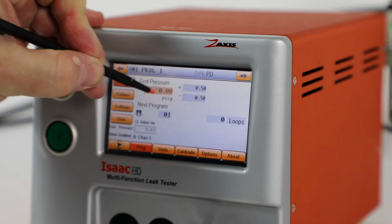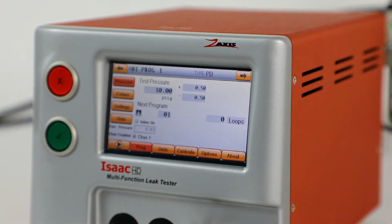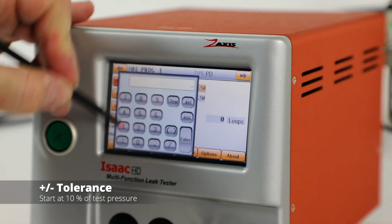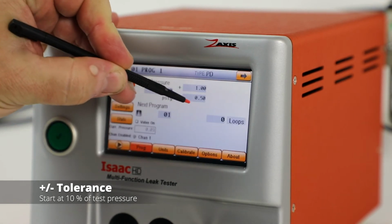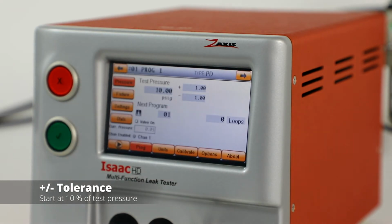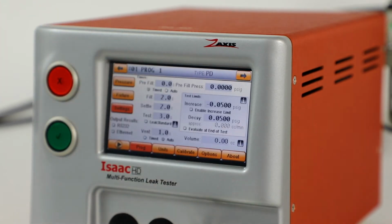So I'm going to enter 10 psi as my test pressure selection. For the plus and minus tolerance, we typically recommend you start at 10%. So we'll move +1 and -1. This will allow for a test pressure of 9 to 11 psi. Jumping ahead to the settings, the actual test setup, this is a great place to start.